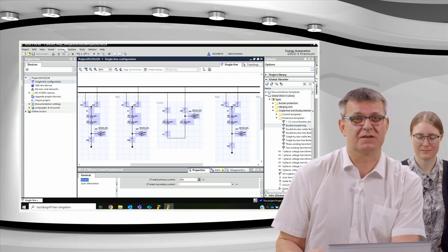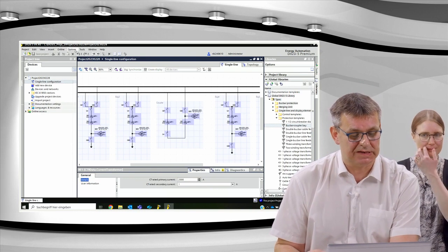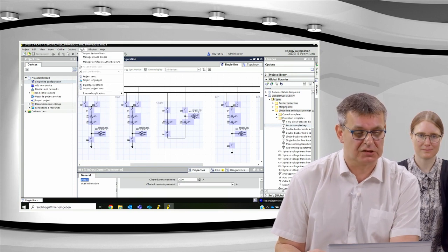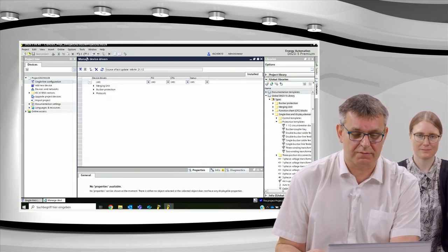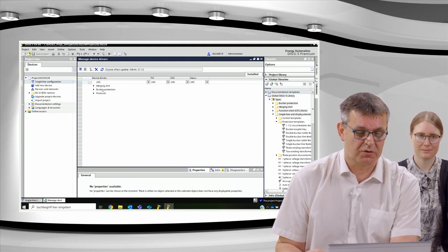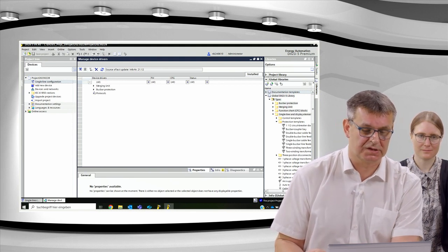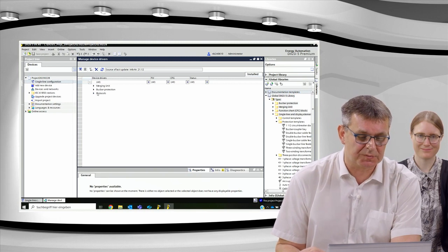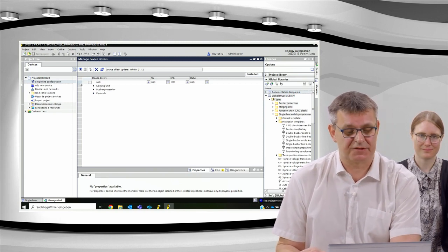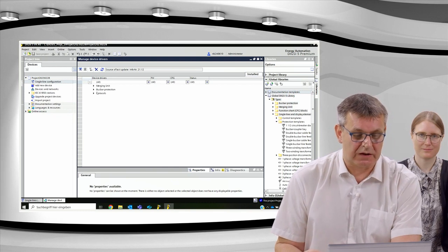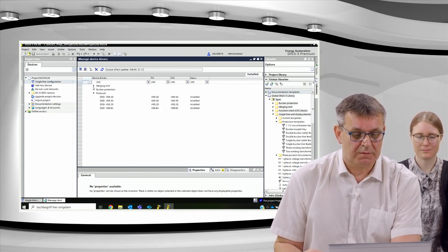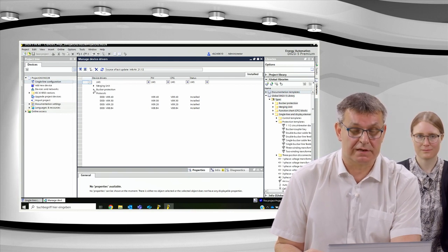Before that, you need the device drivers, the DIGSI device drivers, the DDDs. I will just show you which DDDs I have imported. We select Tools and go to Manage device drivers. And so you see that I have imported device drivers of the communication protocols. More necessary in the next tutorial, when we are talking about the distributed busbar protection, but also typically necessary in a centralized busbar protection, because nowadays really every device, especially a busbar protection device, has a connection to a substation communication. So here I have several merging units we will need in our last tutorial.